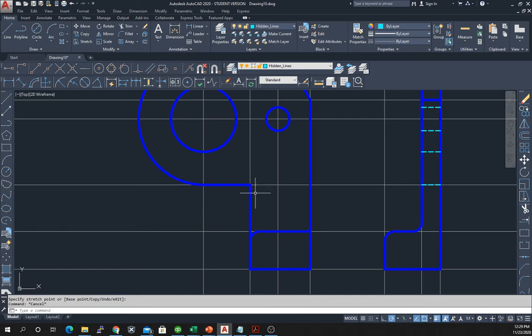And now we have to put in a fillet here for a 0.5 inch radius. So again, we choose fillet, type, come down here, type R.5, enter, and then type this edge, and, oh, must have missed something.